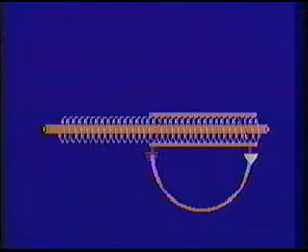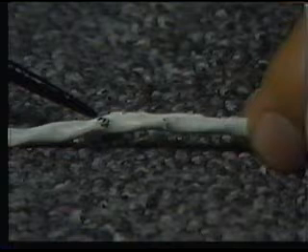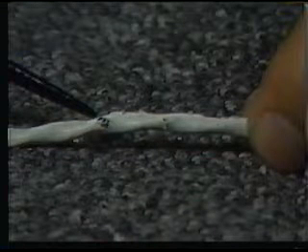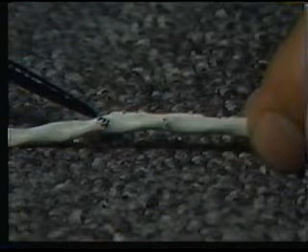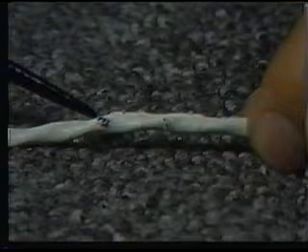It is important to note that the ground for the shield could be anywhere in the middle of the segment and produce the same ill effects. It is imperative this condition be prevented. It is equally imperative that such conditions be found and corrected using accepted electrical maintenance practices. In many cases, the shield inadvertently and intermittently touches the structure through its routing, making for a difficult situation to detect, much less repair.